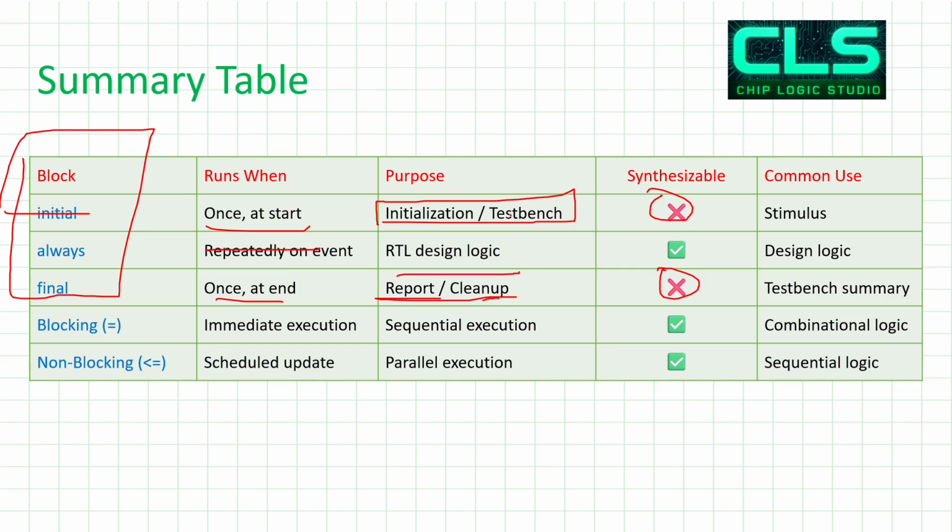For report and cleanup, cleanup is also a phase in UVM and SystemVerilog. Cleanup is like whenever you are printing a report or any result or scoreboard, you use the final block. And yes, the common use of initial is for stimulus, because we are using it in the test bench to give stimulus. For design logic, as you have seen earlier, like RTL design, we write the logic in always blocks. And for test bench summary, like scoreboard and everything, the result will be printed in the final block.